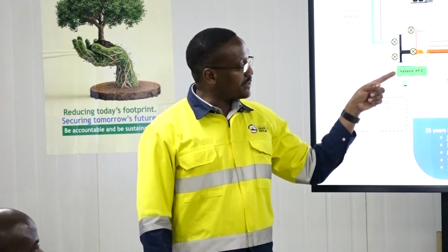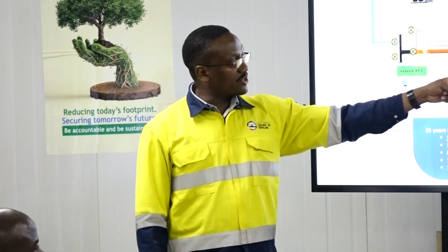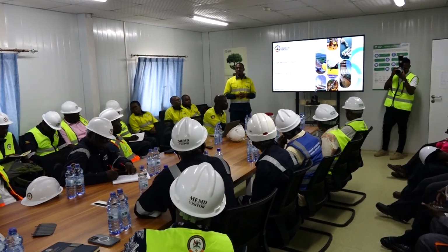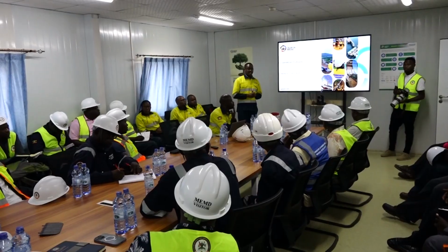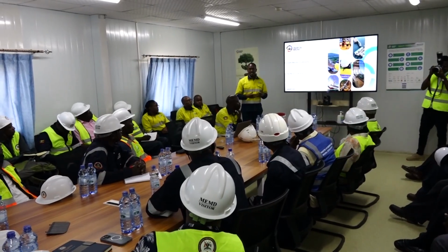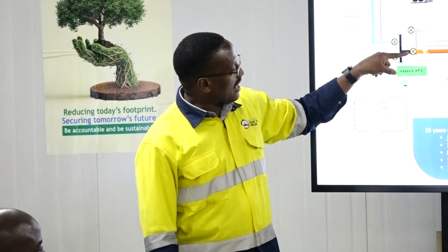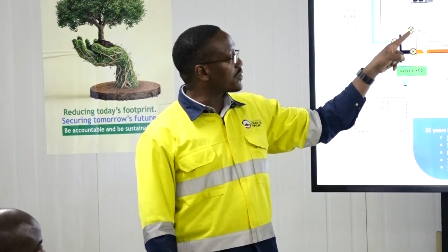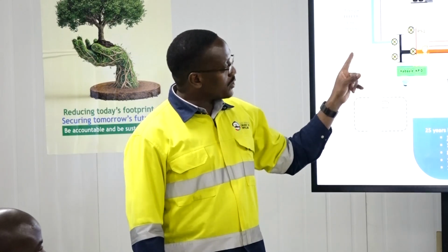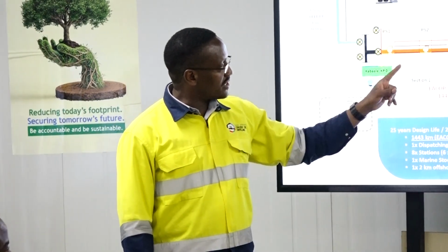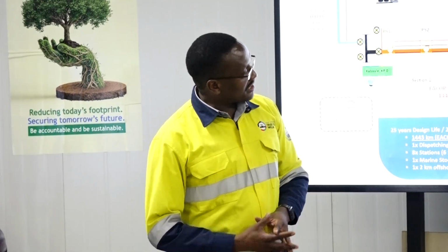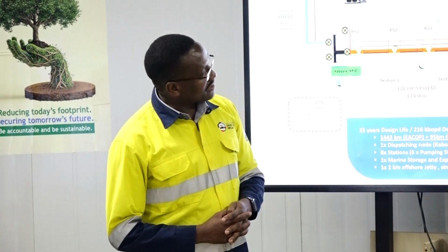The oil arrives here at PS1. At PS1, the oil can either go to the East African Crude Oil Pipeline or to the refinery, which is just adjacent to PS1. So we have allocation meters, and then we have this fiscal meter: fiscal meter into EACOP, fiscal meter into the refinery. Okay? So for EACOP, we talked about pumping station 1, which is here, pumping station 2. Then we will have the oil flow all the way to the tanks and the Indian Ocean.